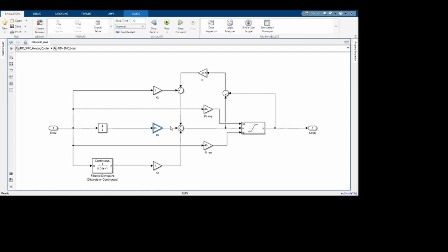Once I substituted that, I had to solve the second order differential equation, and I kept my damping ratio as 0.5 and my settling time as around 2 to 3 seconds. Once I calculated those gains for kp, ki and kd, I assumed kd as 1 for both heating and cooling. I will explain to you why later. But for now, from my calculations, I got kp as a whole number of 1 and ki as almost 0.48. I could also keep it 0.5. It won't make a difference.